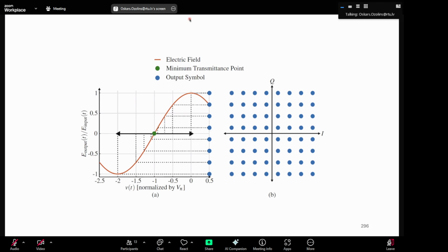So here is also a good graph to understand why a very high peak to average power ratio can lead to problems. If you have an average power, which is a value, and then you have peaks of power which go pretty high, then you will start to get nonlinear impairments due to the modulation.